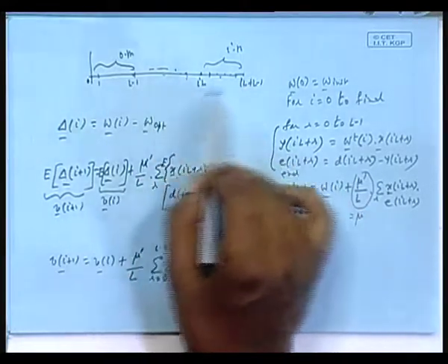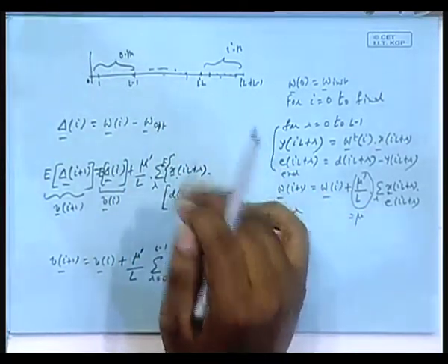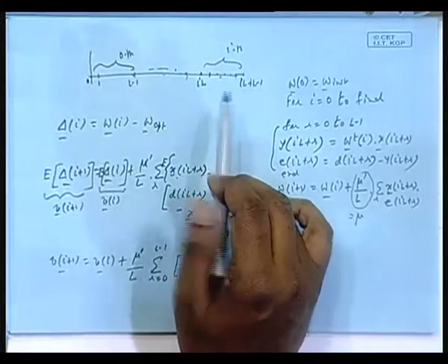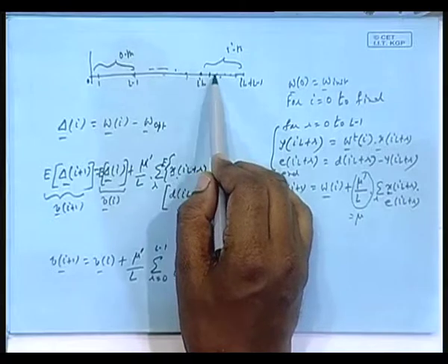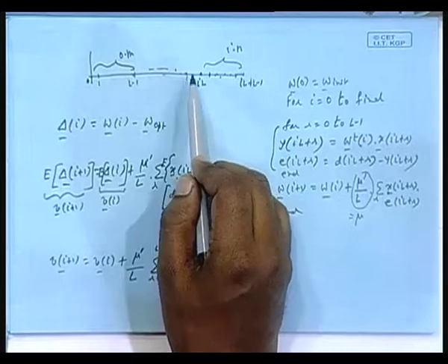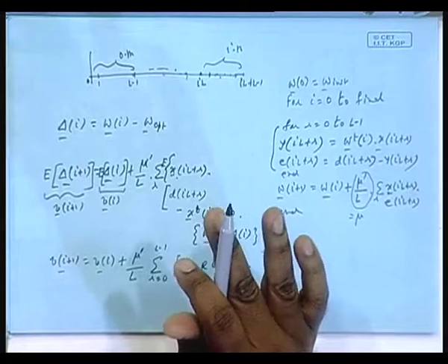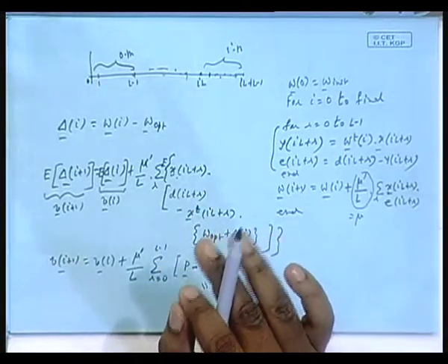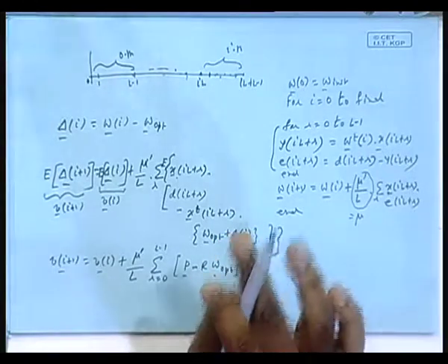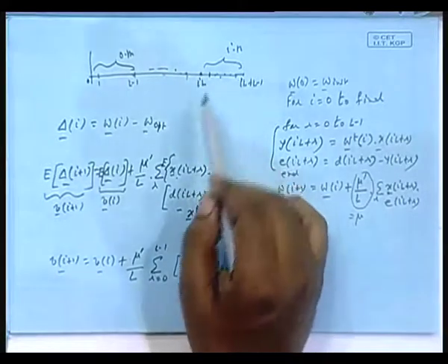there is a correlation in the input. So through that correlation, Wi depends on the data vectors or data for the current block itself. Furthermore, when R equal to 0, R equal to 1, R equal to 2, this part of the data vector overlaps with the previous block, and that was used in the evolution of Wi, isn't it? Still we make this assumption, and it works, that Wi is independent of, not just uncorrelated, statistically independent of the data vectors corresponding to the current block.